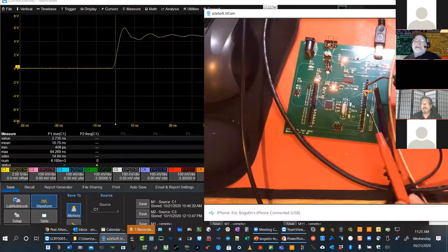But you can say, well, wait a minute, this is a 10x probe. Isn't it like a meg impedance? Isn't it really high impedance? You've got to have current in an antenna in order to radiate. How do you get current? Well, at DC it's high impedance, but that's part of understanding your equipment. That's what we call situational awareness, being aware of the electrical properties of your system.